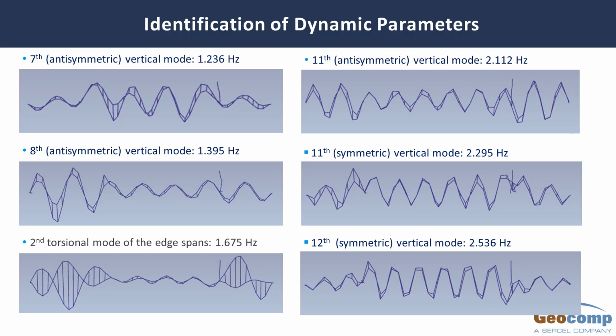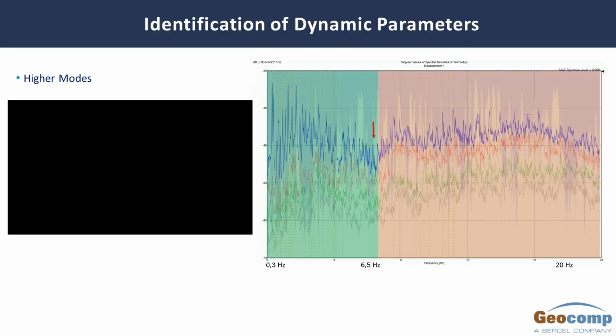If you want to take this further, you are going to see much more complicated shapes. Now, these high mode shapes are generally more related to individual components of the bridge, not overall behavior. For instance, at 10 hertz, 20 hertz, 30 hertz, if you have a mechanical component on your structure, you are going to see it behaving or moving independently, decoupled from your structure. So those are the things we look at in the higher frequency range. In the lower frequency range, we are looking more at the overall global shape, which can create high forces when it comes to earthquake and wind.